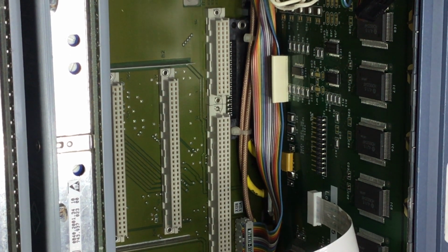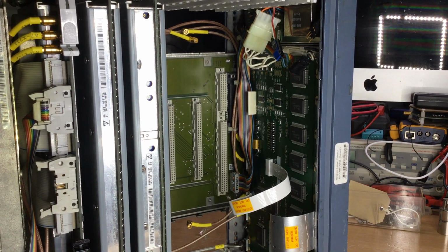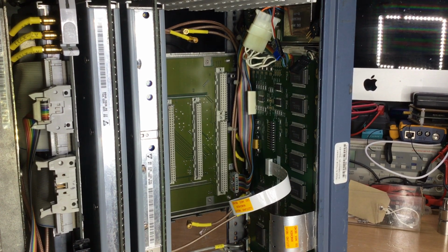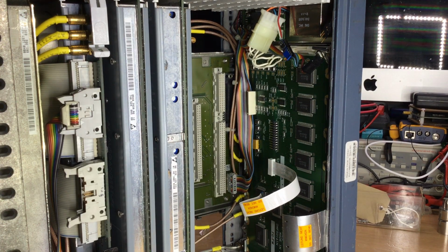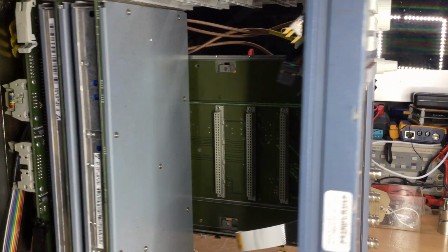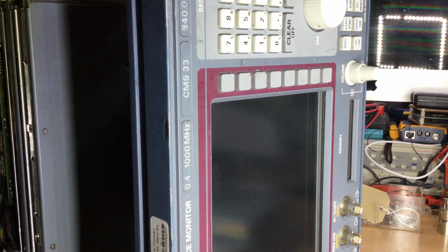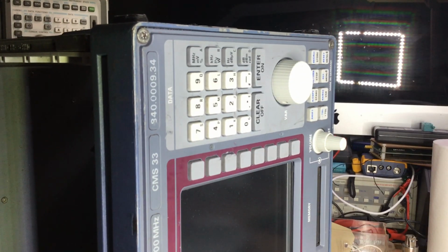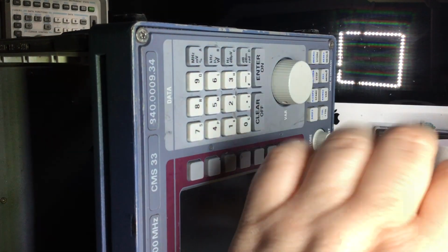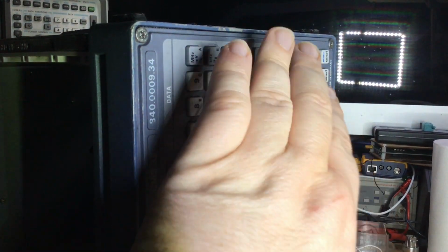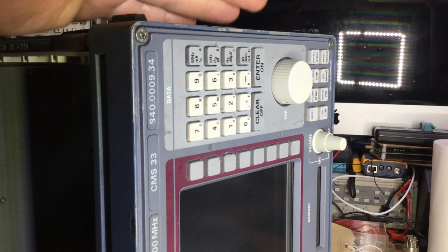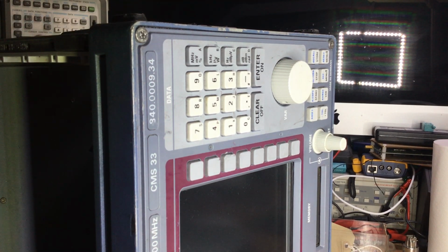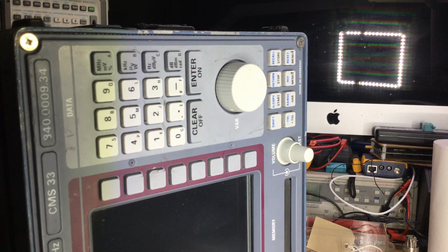So it is looking possibly, depending on what I read in the service manual, that we may have to remove a front cover to get to that more, because I've got a feeling I'm going to have to take that encoder out of the unit altogether. I'm going to have to take the front panel off, remove this encoder knob, and then the encoder assembly, and remove it if we need to strip it down to clean it, which is probably what's needed. So yes, that's going to be interesting.